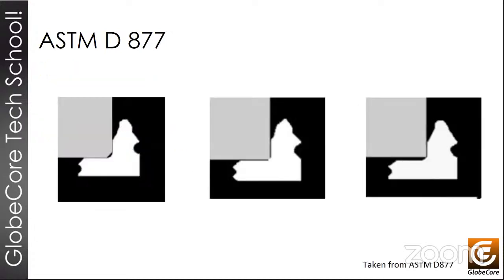Next slide, please. Once again, the edges of electrodes must be sharp. Rounded edges will generate higher breakdown voltage values. That will cause, if we have unacceptably bad oil, it to show acceptable BDV values. So you can generate high values in degraded oils, which could confuse us, and it could cause us to accept a bad oil for use that should actually not be used. And the cleaning of the electrodes is also very important. The electrodes must not have any corrosion on them because corrosion can generate falsely low values. Next slide, please.